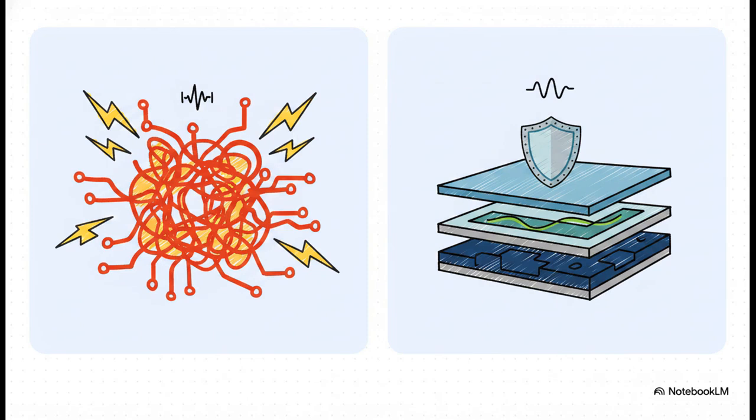Professional PCB routing is kind of a dark art. Amateurs love to rely on autorouters, but that usually just accidentally creates massive antennas for electromagnetic interference. Professionals use strategic layer stack-ups. They know that physically separating the analog ground from the digital ground is the only way to prevent the microscopic electrical noise of high-speed digital switching from completely destroying the accuracy of your ADC readings.